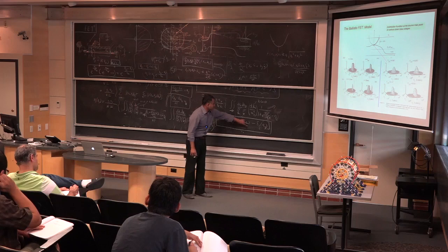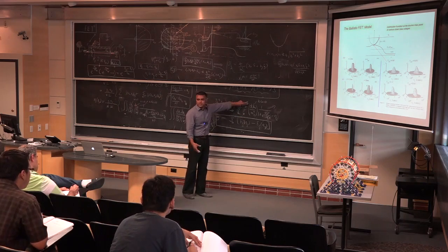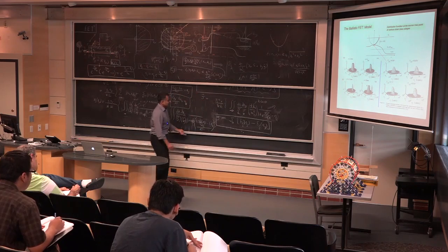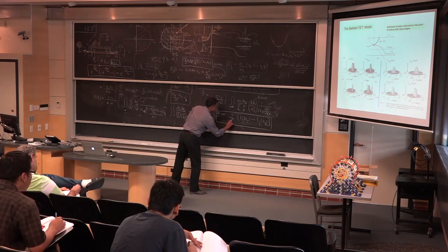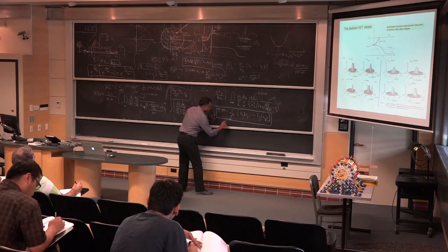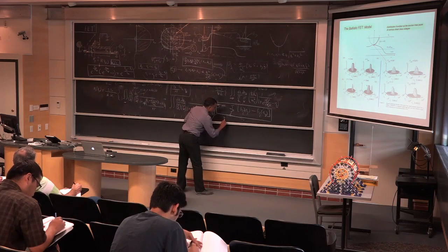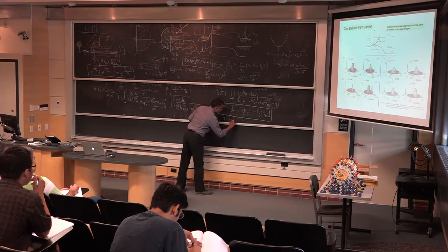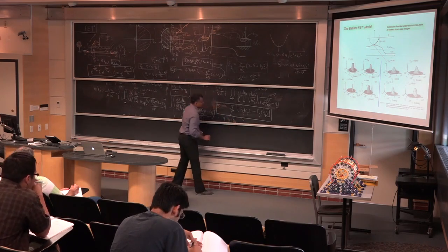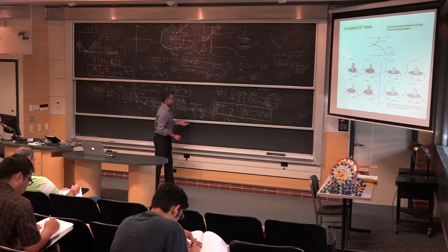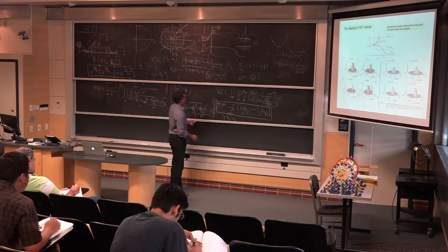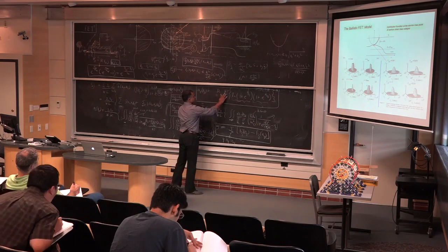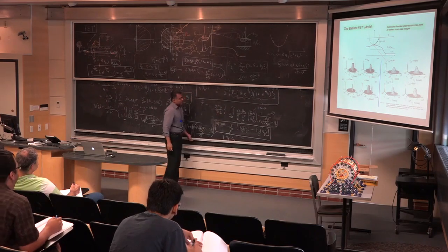Again, this is just an expression for this integral. There's really nothing more fancy than that. What is that J naught? The J naught will be a product of 3 things. There is Q. If you remember, we had derived something called the quantum carrier density times some sort of an injection velocity. I think people go back and forth on this. But if you see the carrier density, it has all these things: density of states, kT, it will also have it there.